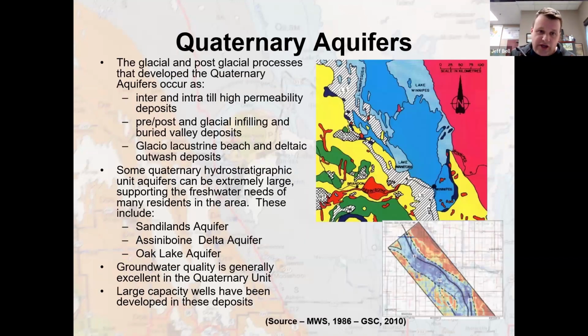Of course, lying on top of all of this bedrock is a fairly thick sequence of Quaternary or recent deposits. These are all deposits that are primarily glacial or lacustrine, or lake-type deposits, where we've had former glacial lakes that have drained and we've been left with their deposits. So a lot of till. Till is mostly sands and gravels that are held in a clay base.